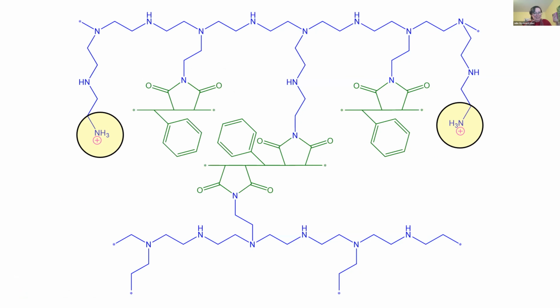So as I begin wrapping up here, I want to briefly go back to the idea of developing material science solutions to reducing food waste that bridge both innovation and pragmatism. Bring your attention back to the chemical structure of this coating that we were using in some of these experiments. These cationic groups enabled our materials to have dual antimicrobial activity, which was important, especially as we increased organic load.